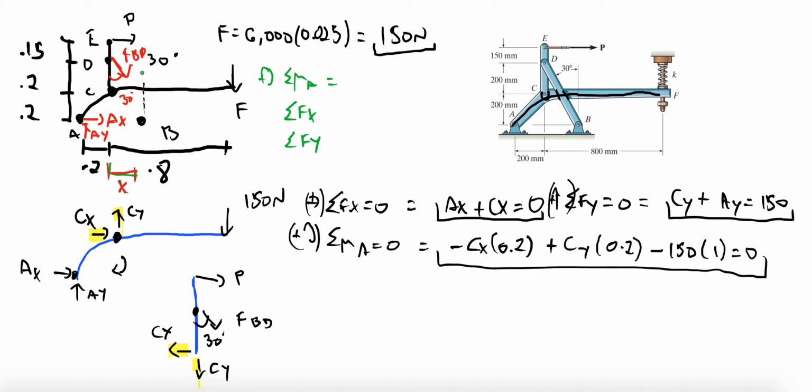Look, FBD is also acting at D just like it's acting at B. It's the same two-force member that's going through those 2 points. So that force can be just considered to be transferring over from one point to the other, right? And since we're not concerned with link BD, we don't have to worry about it for the general assembly of the mechanism. We can analyze it the way I have it now.